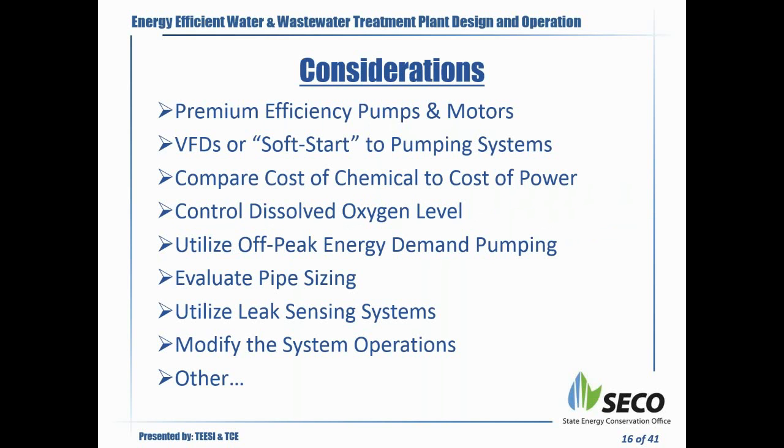Some other considerations on a water wastewater treatment plant is that you should be looking at premium efficiency pumps and motors. That's what we'll be looking at, seeing what you have right now and what could be installed over there. Using VFDs for soft start to pumping systems, so that's something that we'll be evaluating. Ideally, we want to look at VFDs more than a soft start kind of a device, as it has many useful applications. But anyways, when we're going through the facility, we look at those things.